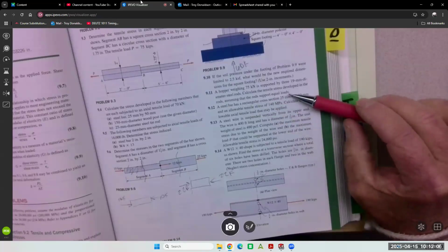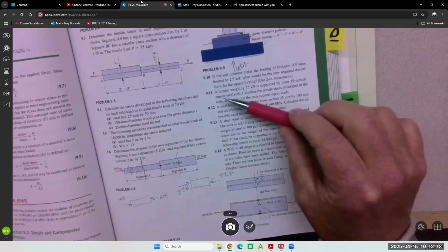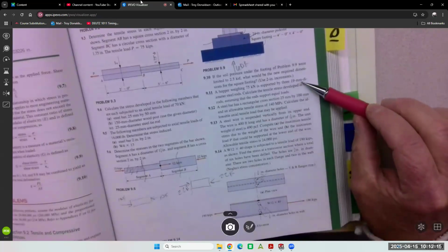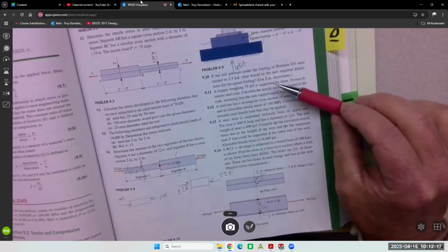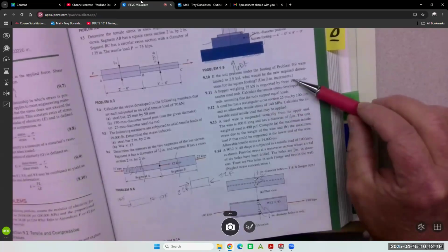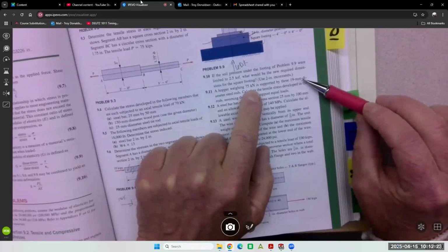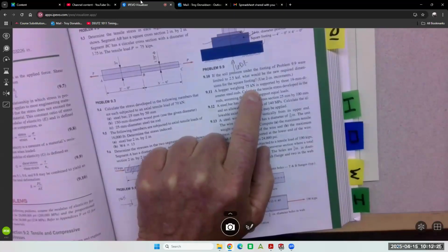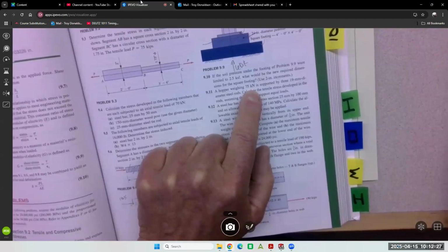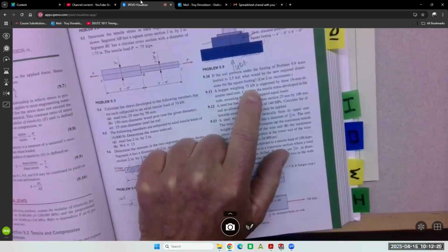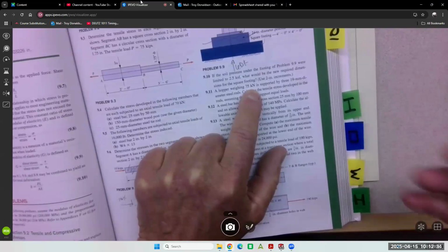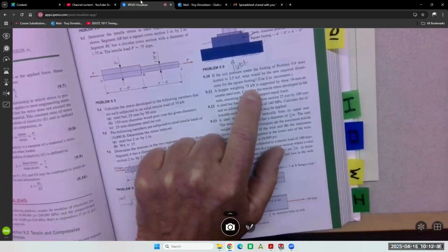So we have rods of equal loads. How many of them? Calculate tensile stress on the rod. And the hopper is supported by 3 19mm diameter rods. How'd you do this one? 75 kilonewtons, 19mm in diameter, 3 rods. Yeah, so it says equal loads. That one's pretty simple. You can just calculate that 1/3 of the load goes to each rod.